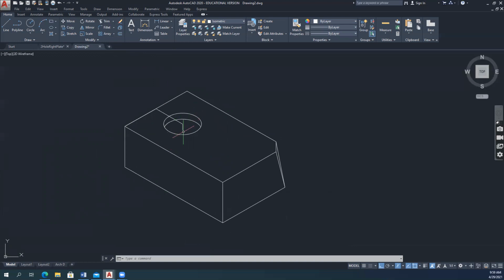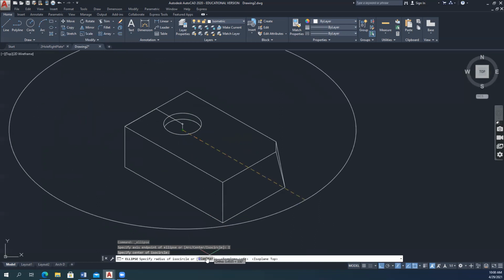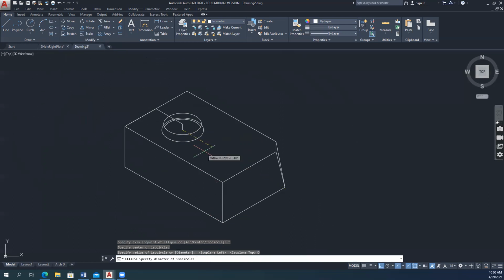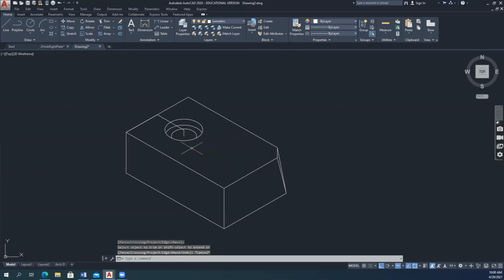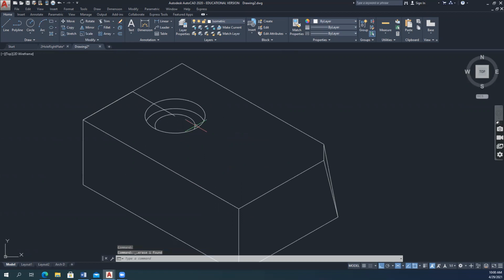And now we need to actually have the hole that's going to go entirely through all of this part here. So I'm going to do this again, the axis end. I'm going to hit ISO circle. The center point is going to be right here. I'm going to hit F5 to get this in the top plane. I'm going to go down here and click diameter, and I'm going to type in 0.5 for the diameter. Then I'll go to trim, right click, and trim these holes here. Right, so we no longer need that line, so we can delete that line there.